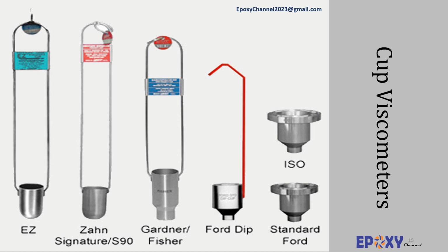Viscosity cups are used to determine a fluid's kinematic viscosity and are typically made of anodized aluminum with a stainless steel orifice. The cup is filled with the fluid and the orifice is placed at the bottom of the cup, where fluid can pass through. This relatively simple test involves placing the fluid in a container with a small opening at the bottom. The fluid is allowed to flow through the opening in a precise amount. The time it takes for the fluid to pass through the opening is measured and correlated to the viscosity through the use of charts applied for the given cup.